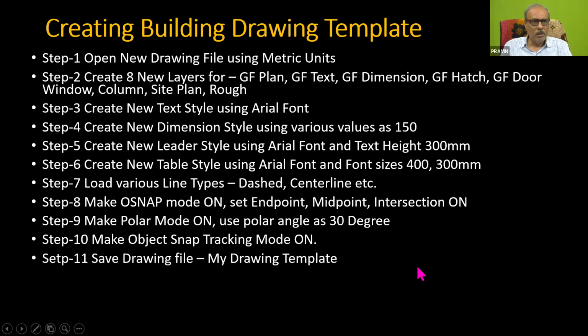Then the next step is to save this drawing file by giving it the name my drawing template. So that is the important step. So dear friends, by using these 11 steps, you can save your settings in a drawing file and give it the name my drawing template.